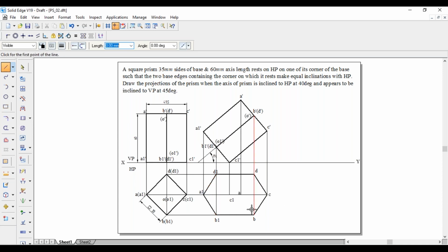Next, once we draw till this one, next, coming to the top face. So out of 4 shorter edges, 2 are joined. That is DC and BC are joined. We are left with AD and AB. So AB is this one, this line from A dash to B dash. A dash, D dash will be behind that one. So both are very nearer to the observer. So it is visible. So BA and AD are continuous lines.